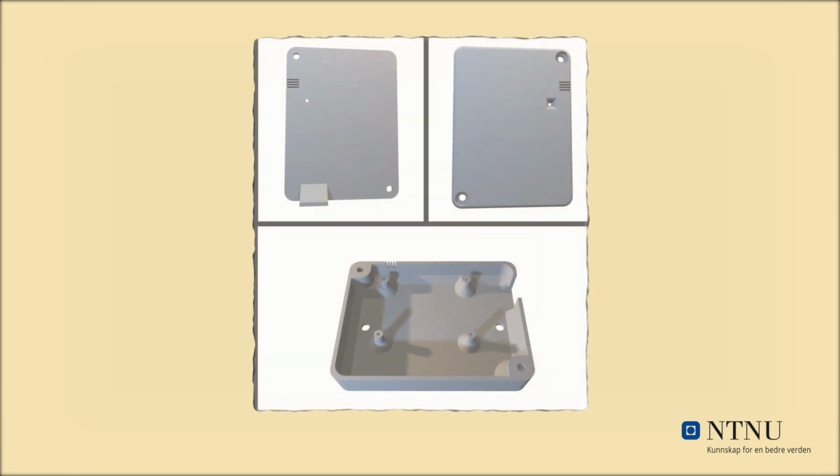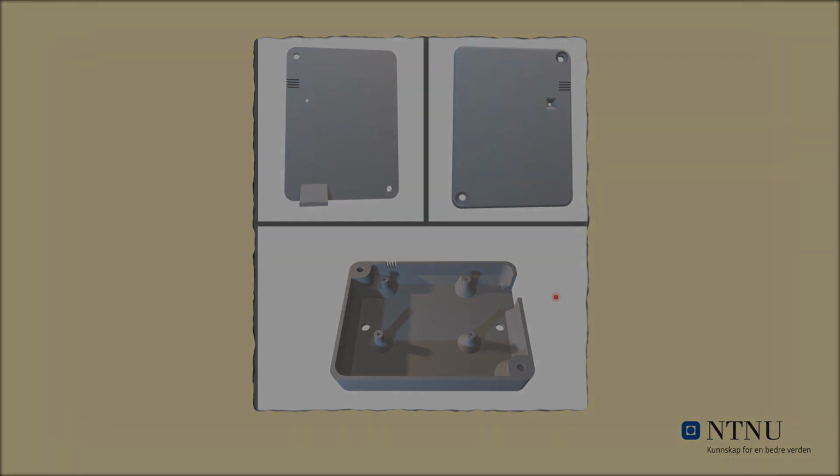This is the 3D design of the casing used. This was made in Fusion 360. The top one here has a hole for the brightness sensor here and here, and has slots here for the microphone, also located here. The bottom part has 4 holes for mounting the PCB and 2 holes for mounting it onto a wall. It has a hole for inserting cables, and it is closed by this extruding part on the top side. It will need to be cut manually to allow cables to get in, which will make it more dust-proof. And that's it for this physical part.